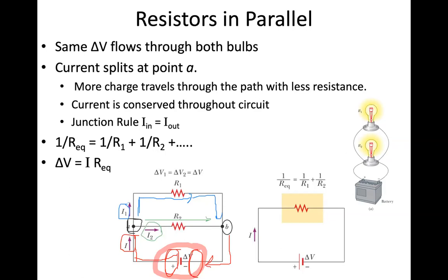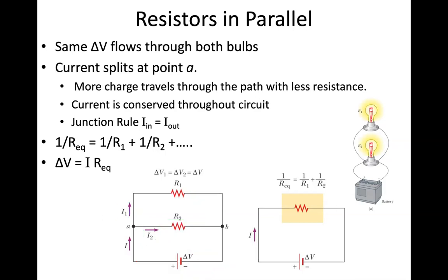So what I get is current that now I have to specify. What is the current flowing through resistor 1 versus what is the current flowing through resistor 2? When we were talking about series, we didn't have to ask that. We just said, what is the current? Because it was the same throughout. But now what happens is there is something they share. So in series, they share a current. They all have the same amount of current flowing through it. Well, what about in parallel? What do they share? Well, I'm going to give you the answer.